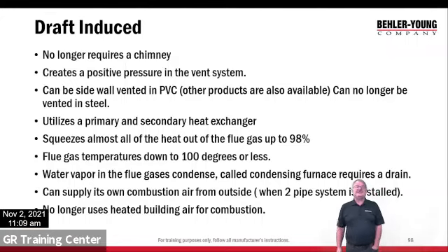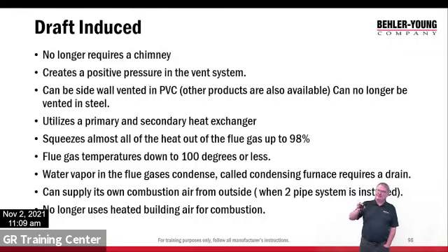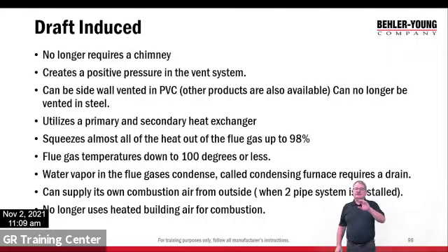So in draft induced, 90%er, plastic pipe. No longer requires a chimney. 80% still does. Creates positive pressure in the vent system. So the furnace is in a negative pressure, but the vent pipe is a positive. Can be sidewall vented with PVC or other products also available. Now, you want to be careful with that one because certain things can't be used with PVC.